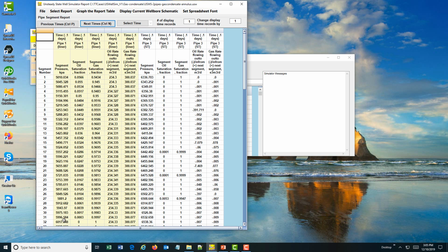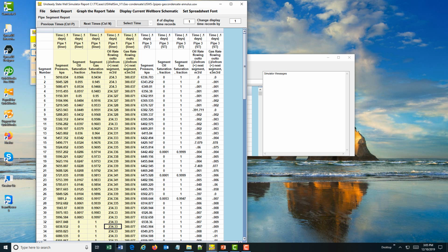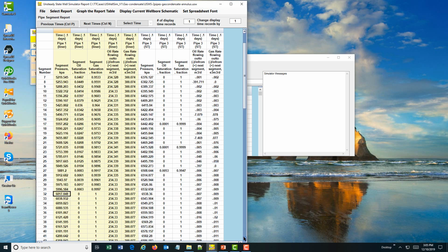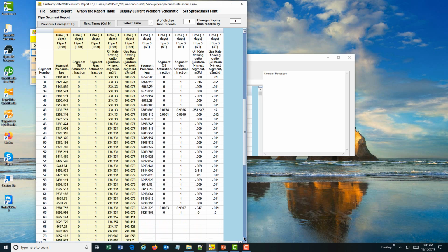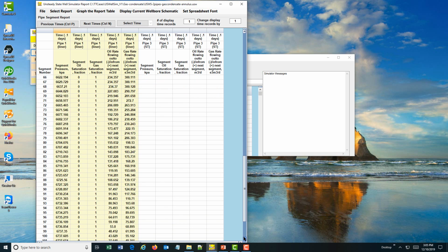And you can see that when the pressure is 6000 in the pipe, there is no oil saturation. If you go from the bottom, from the very end of the horizontal well, we can see that the oil rate coming in is increasing as it accumulates in each segment. Each segment is contributing reservoir input.